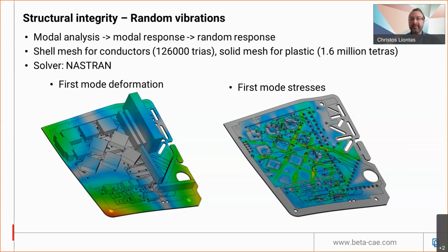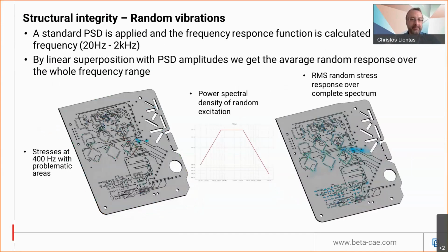We have performed the simulation in Nastran with shell mesh for conductors and solid mesh for plastic. And at the next stage, for each frequency in this spectrum from 20 hertz to 2 kilohertz, we calculate the modal response. So we calculate the stresses at each separate frequency.